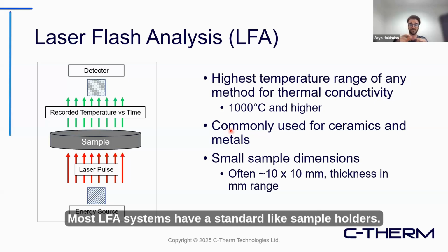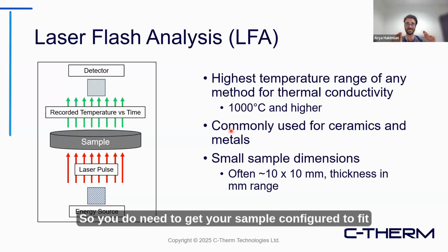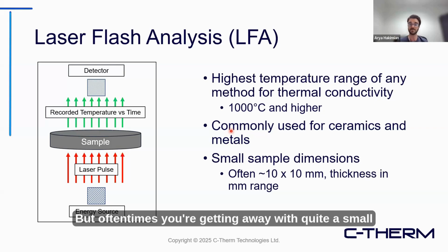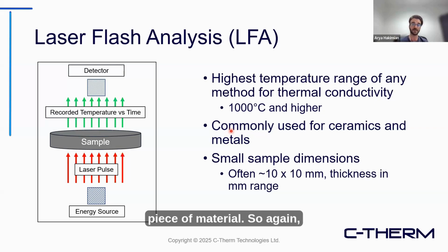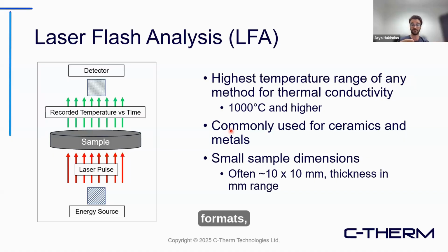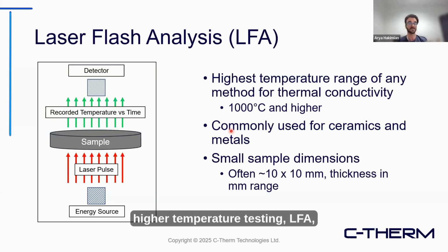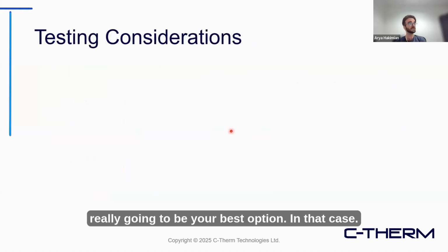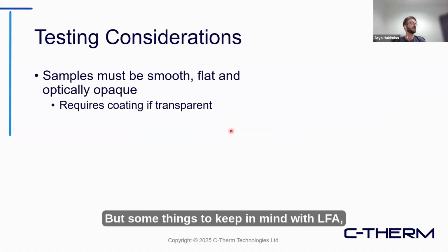Most LFA systems have a standard sample holder, so you do need to get your sample configured to fit into whatever that dimension is. But oftentimes you're getting away with quite a small piece of material. So again, something that's certainly good for smaller sample formats, higher temperature testing. LFA really going to be your best option in that case. But some things to keep in mind with LFA.